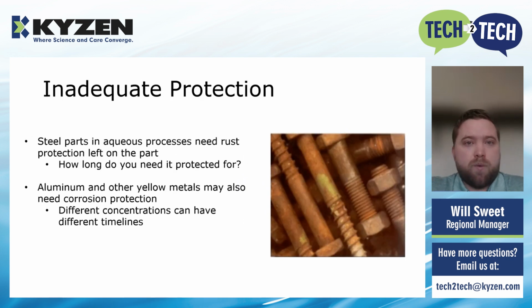Something else that can go wrong with improper concentration management is inadequate protection. This comes into play in particular with steel parts, because steel rusts, or at least mild steel and cast iron, things like that. Steel parts in aqueous processes need rust protection left on the part after it has been cleaned. So the most important question to ask is, how long do you need it protected for?